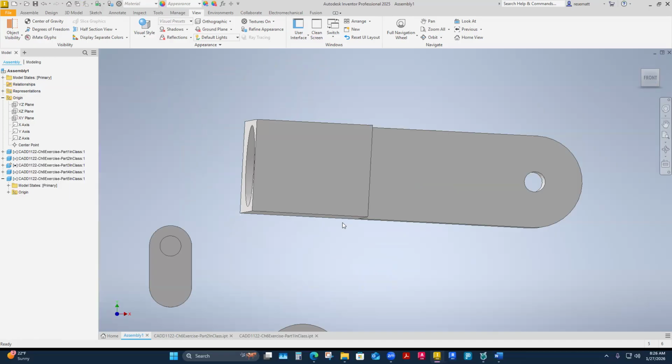If I'm thinking about putting this on a drawing specifically, my front view is going to come in naturally, even on an assembly. When I go to place an assembly on my drawing, just like a part, it's going to be a base view of the assembly, and I'm going to be able to rotate it. But if I'm in some weird, wacky orientation, it doesn't make sense as a drawing view per se. So I don't usually just come in here and ground one randomly.